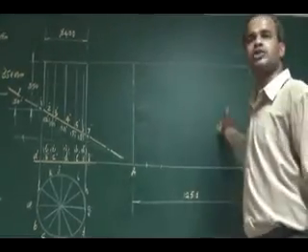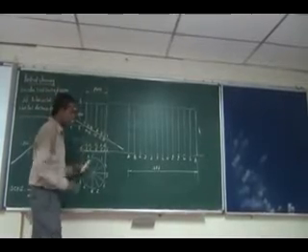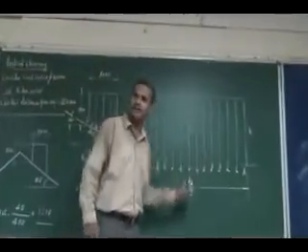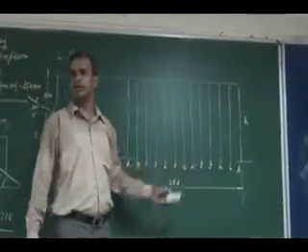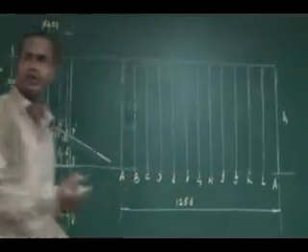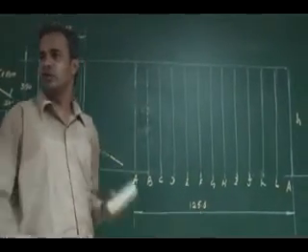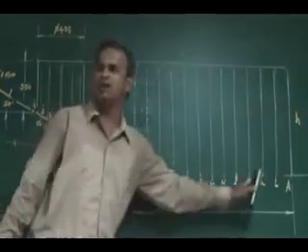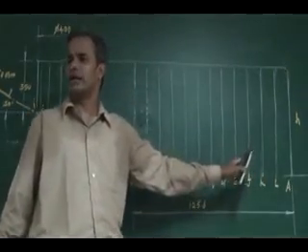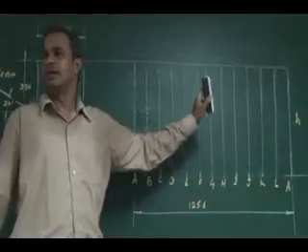Try to represent the generators and cutting points in your development. You have 12 generator locations. You try to mark those 12 generator locations and show the 12 generators in your development also, right? So generators will be from A to B, it will be 125.6 divided by 10.4. You mark 10.4 and try to show all the generators in your development in 2H pencil. Something like this, right? Is it clear?